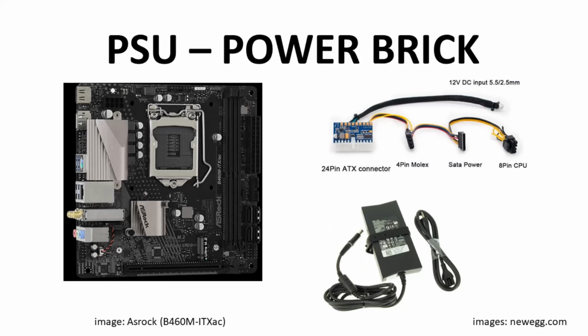The Pico power supply then converts the higher voltage down to everything that the motherboard needs: 12 volt, 5 volt, 3.3 volt. Using a Pico power supply takes some planning. The Pico PSU must be rated to deliver the power you need for your system. The Pico PSU also needs an adapter that goes to the back wall of the case for connection to the cable from the power brick. There are different connection types, and everything needs to match.